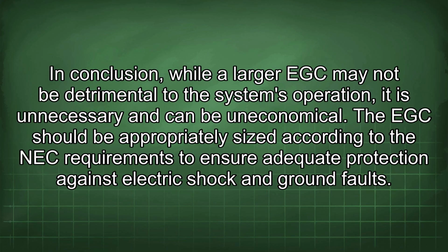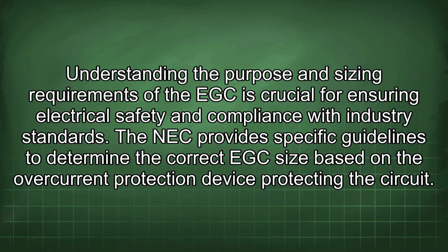In conclusion, while a larger EGC may not be detrimental to the system's operation, it is unnecessary and can be uneconomical. The EGC should be appropriately sized according to the NEC requirements to ensure adequate protection against electric shock and ground faults. Understanding the purpose and sizing requirements of the EGC is crucial for ensuring electrical safety and compliance with industry standards.